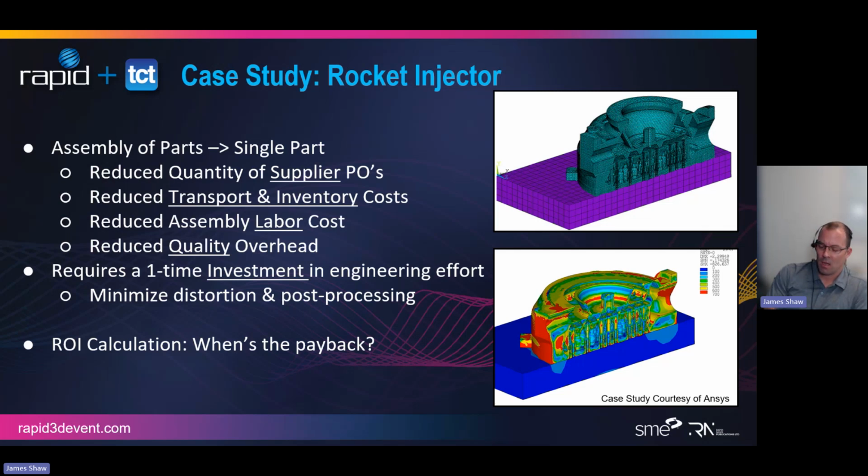This particular part, so many manufacturing challenges were solved just by going to additive. Now, it wasn't the alloy that saved the world, right? It wasn't the machine that made everyone look like legends. It really was a combination of technologies, processes, redesigns. And so what happened? Single part. You could not make that geometry in a single part by doing it any other way. You just can't machine or forge or cast or really get into some of the small details on the inside. Reduce the number, and these are things that maybe engineers don't think about. Reduce the quantity of purchase orders from a supplier.